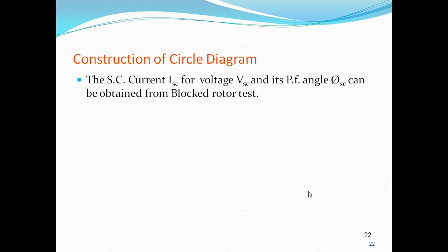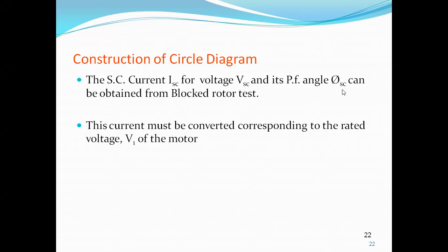Then from the short circuit test, we take ISC, the short circuit current, VSC, the voltage, and the phase angle phi SC obtained from the blocked rotor test.